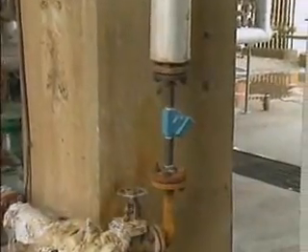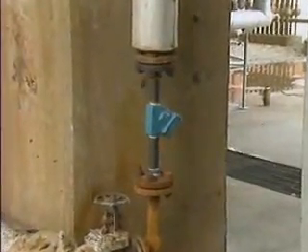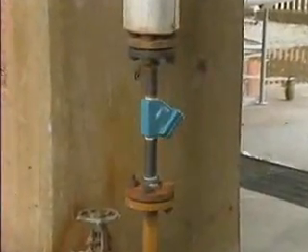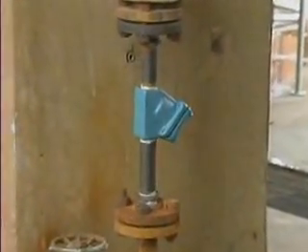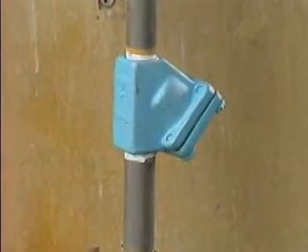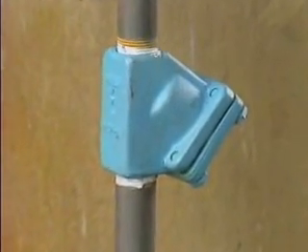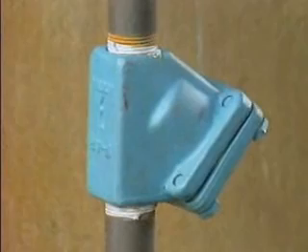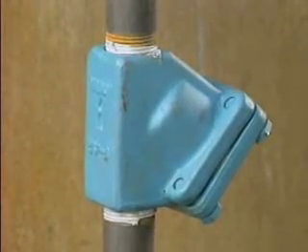Most thermostatic traps discharge condensate intermittently. The time it takes for condensate to discharge depends on the amount of condensate in the trap's drip line. The more condensate there is, the less time it takes to cause the trap to discharge. Thermostatic traps are also excellent at removing air.